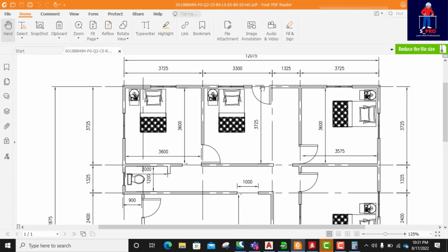That's good. So this column number 1, 2, 3, 4, I'm going to replicate it here. I'm going to offset this to this. Offset this to this. Offset this to this. So this one is going to be very easy for me. I'll just highlight all the columns on this X axis and offset them by 3725 towards the Z axis.